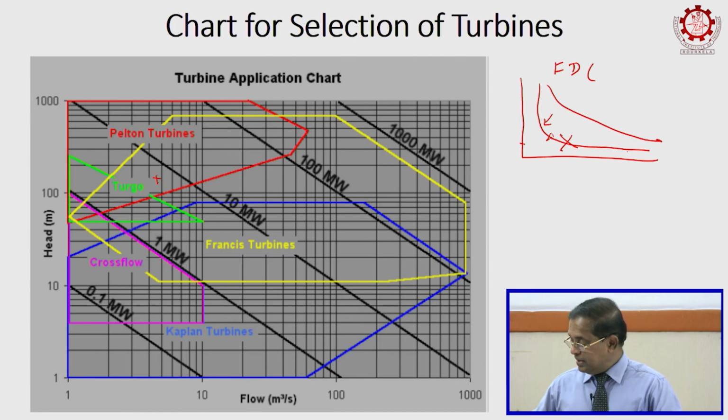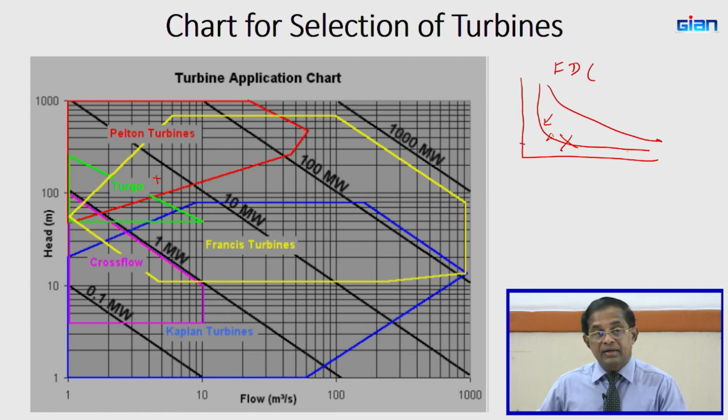So, we discussed here the types of turbines used in small hydropower and special versions like Turgo. Turgo is not used in large hydros, it is especially for small hydros, and Pelton and Francis are both famous for the entire range from small hydros to large hydros.